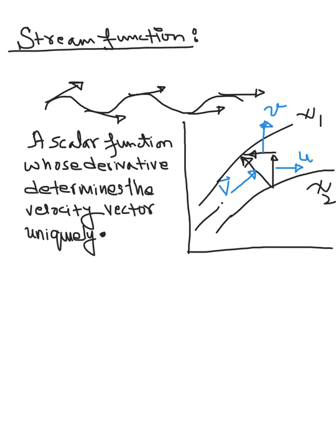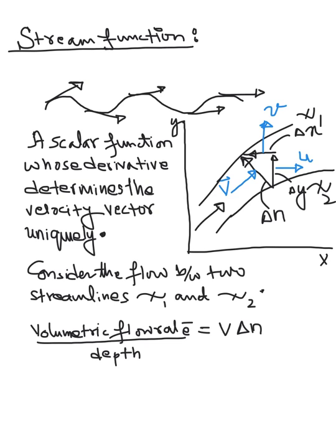This is the flow direction, and this is the direction of the normal to the velocity field, and that normal can subsequently be resolved into two components, del y and del x. So this normal is like the area, so it has two components, del x and del y. As I mentioned, the flow between the two streamlines psi 1 and psi 2 is defined by this geometry.